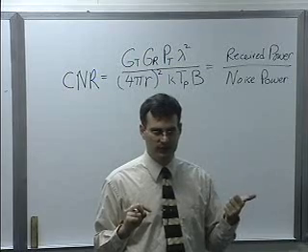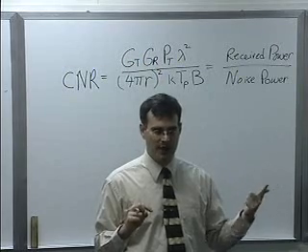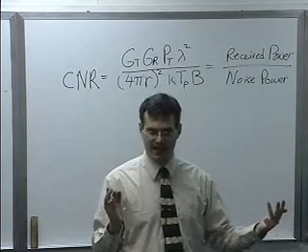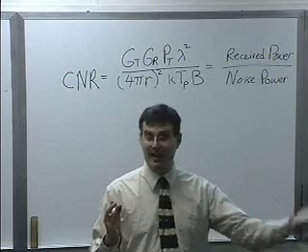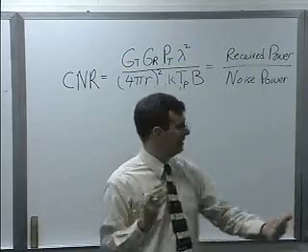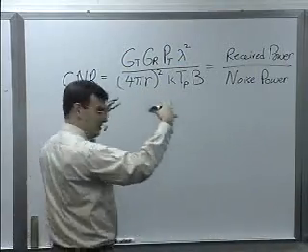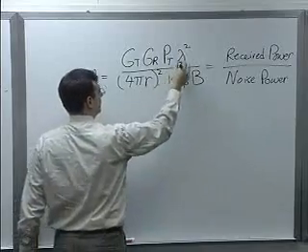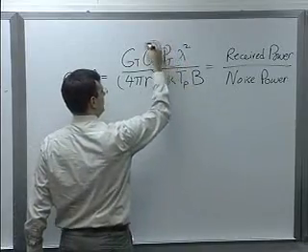Our bandwidth is fixed. Transmit power and transmit antenna gain are fixed. R is fixed. I've got a frequency of operation, so lambda is fixed. The only thing I can change at my Earth station with a dish would possibly be these two quantities here.